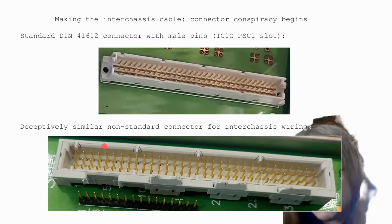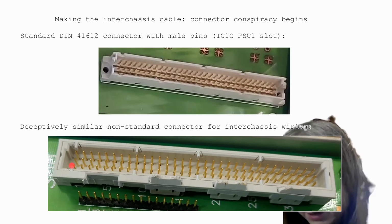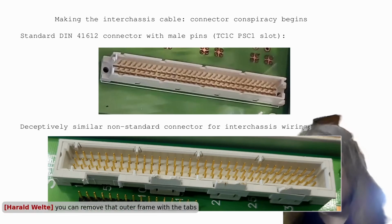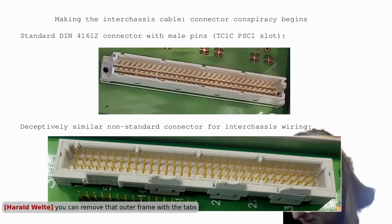look at these tabs. You can't really see in the photo, but they're on both sides. There's this one here and this one here, so they're on both sides. On this connector, there's a total of 8 tabs, 4 on this side, another 4 here. And these tabs prevent insertion of a standard DIN 41612 plug connector.